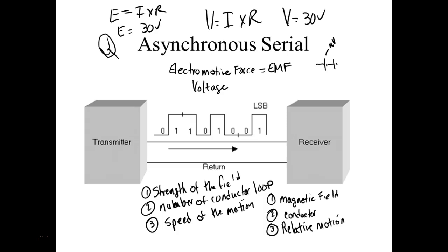To create an electromotive force, we can do it different ways. We can do it magnetically, which is the predominant way of doing it. This is what Alabama Power does. They do it magnetically. This is what your car does. That generator you have out there, and most people call it an alternator, is doing it magnetically. It's spinning a magnet and cutting across coils of wire, which produces a voltage, right? You understand? Now, it's spinning an electromagnet, because what happens is when you're driving your car, what's constantly changing?